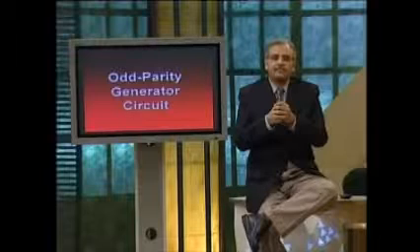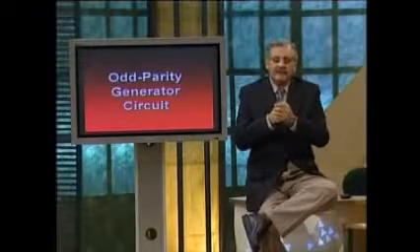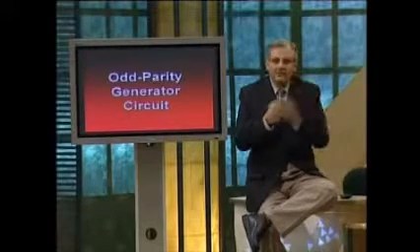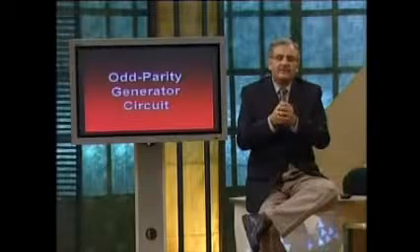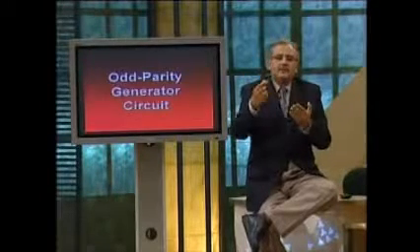सिमिलरली अगर आपके इनपुट कॉम्बिनेशन 0 0 0 1 है तो आउटपुट पैरिटी बिट क्या होनी चाहिए? बेसिकली टू कीप द नंबर ऑफ वंस ऑड, द पैरिटी बिट शुड बी 0. सो सिमिलरली आप ये जो 16 कॉम्बिनेशंस हैं उनकी आप पैरिटी बिट डिटरमिन कर सकते हैं. सो इस तरह आपका फंक्शन टेबल कंप्लीट हो जाएगा. जैसे हमने पहले एग्जांपल एडजेसेंट वंस के केस में किया था, आप 2 किस्म के एक्सप्रेशन इधर से बना सकते हैं, 2 किस्म के सर्किट्स बना सकते हैं.